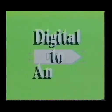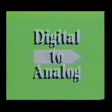Digital to analog converters are used to translate binary words from computers or other digital circuitry into proportional analog voltage levels. DA converters are used to drive analog devices such as meters, motor controllers, audio circuits, or perhaps even video circuits. Before discussing the techniques used for digital conversion, we will examine some common terms and definitions.